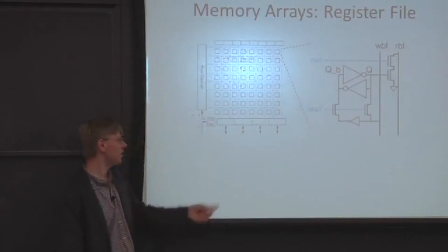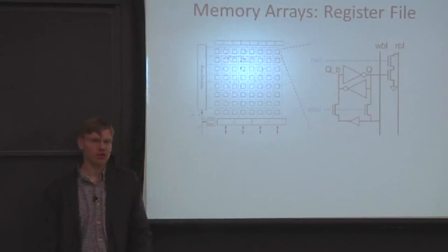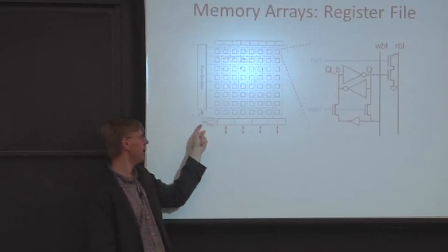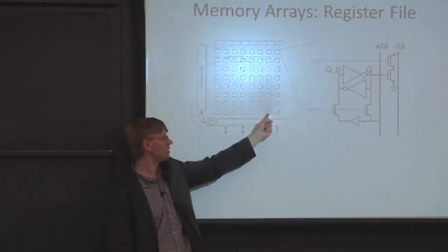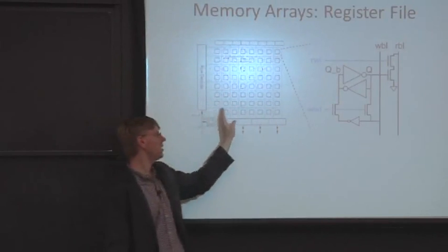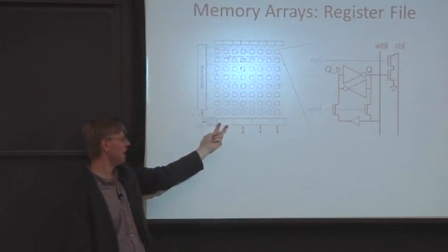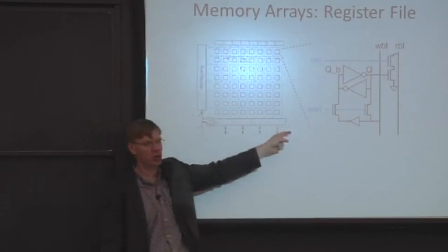So in this diagram here, we have a 4-bit wide readout or write. And we're going to have 1, 2, 3, 4, 5, 6, 7, 8 bits across here. So we're going to need a 2-to-1 column decode. So this is a 1-bit decode here.